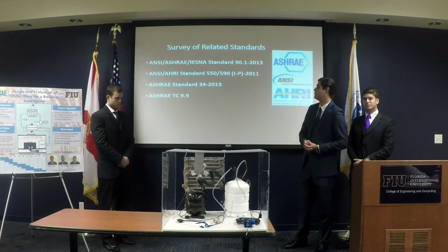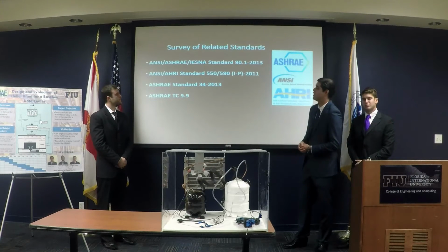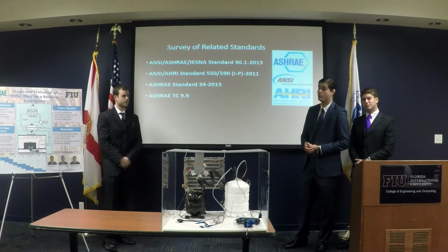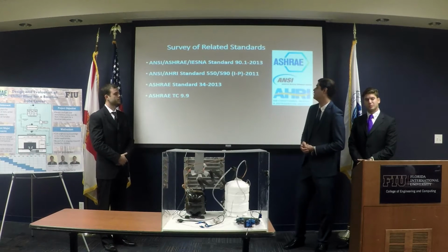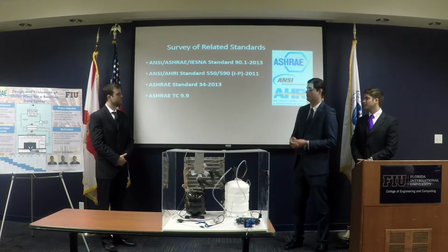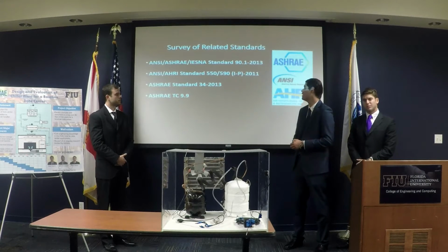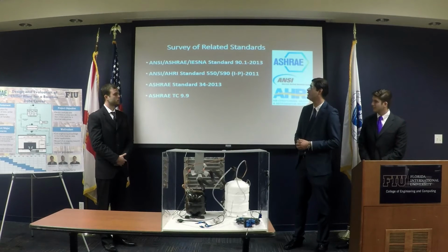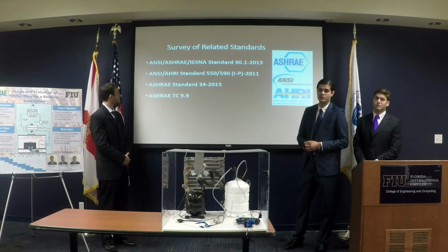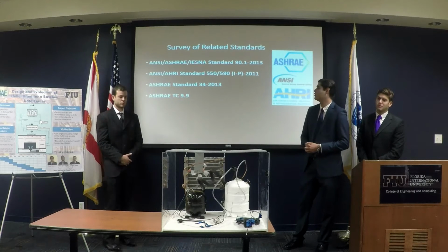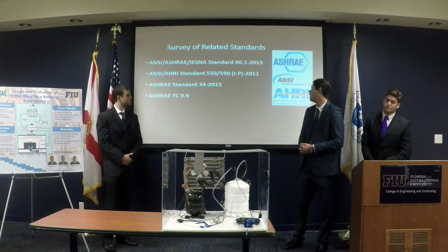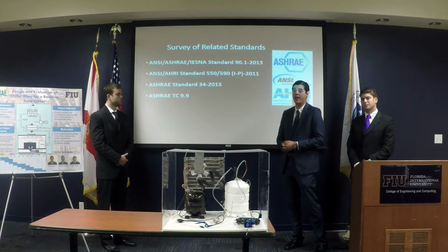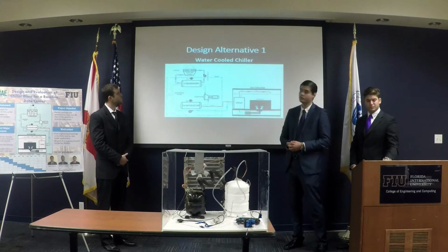So these are the standards to be used in the project. The first one has to do with the minimum energy requirements for buildings and equipment. The second one provides manufacturers, engineers, and contractors designing procedures for chillers, air-cooled chillers, and testing. The third one classifies refrigerants into 6 different categories according to flammability and toxicity. And the ASHRAE Technical Committee 9.9 provides thermal guidelines for data center environments.